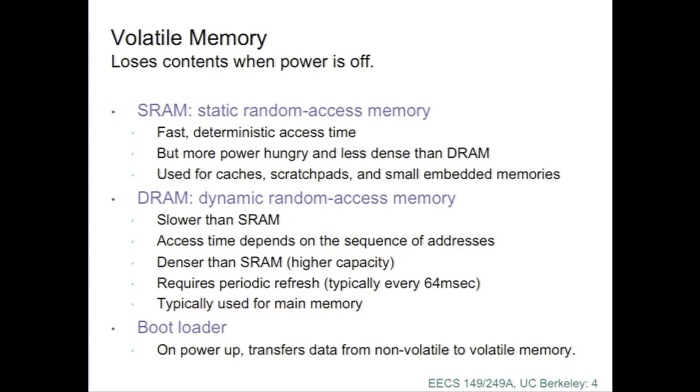Because the access actually takes a while, right? It takes several cycles to complete the access. And the circuit is busy while it's doing that. But if in the next cycle your address takes you to a different bank, then that bank's circuit is not busy. So if your second address takes you to the same bank, then the circuitry will just block the request until the request that is currently going completes, okay? So it can be really very difficult to understand the timing.